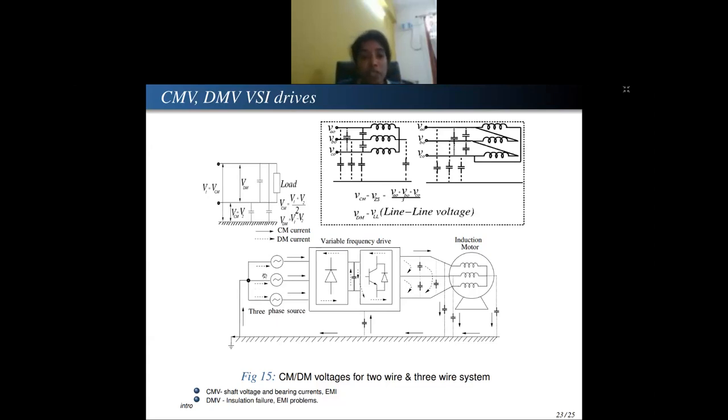effects in this system. If you see in the drive system, the drive is like the propulsion unit of the electrical vehicle. These currents will start from the source and circulate between the lines, and that is called your differential mode current, and come to the ground through the parasitics, again come back to the source and circulate it. That is called your common mode current.